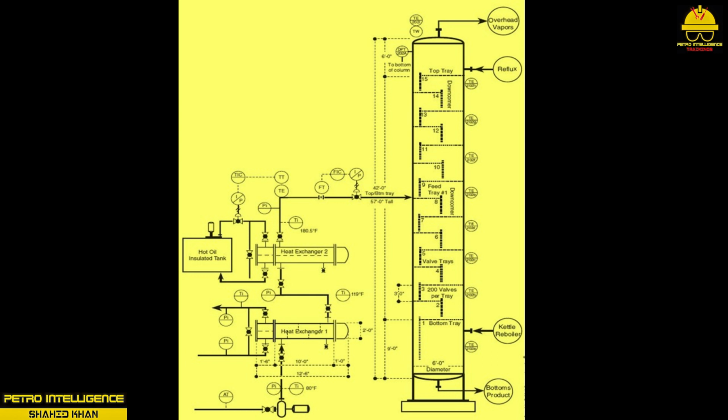The bottom product contains heavier molecules than the side stream or top. To obtain the material balance, add the sums of the three outlet flows. This number should equal the sum of the inlet flow. By knowing the boiling points of the different components in the feed mixture, an operator could determine the approximate material composition and the place on the tower each component will exit.